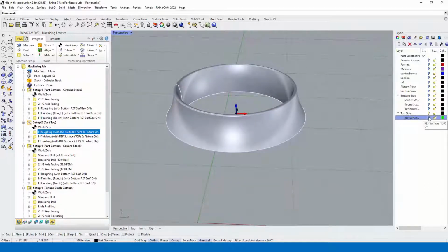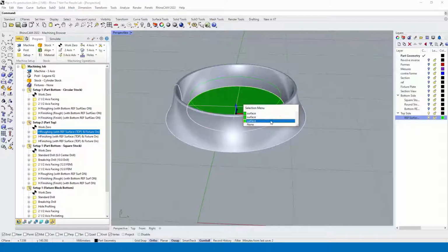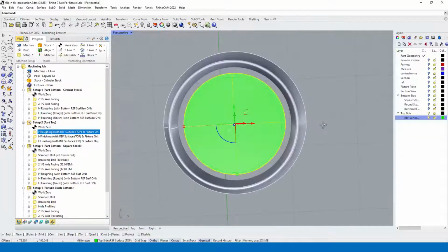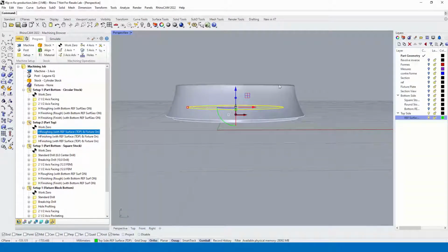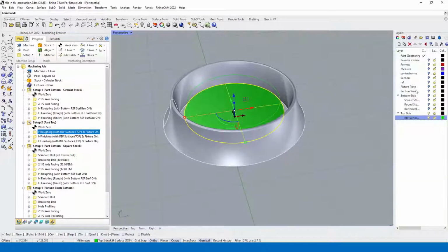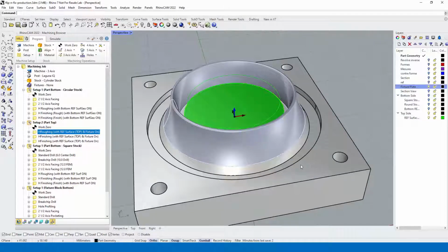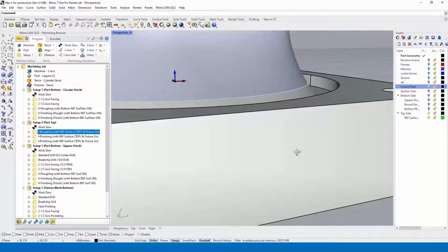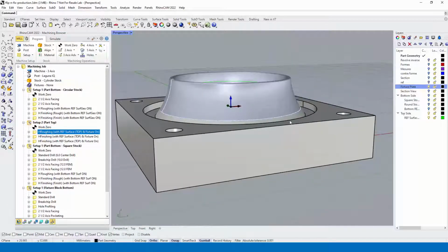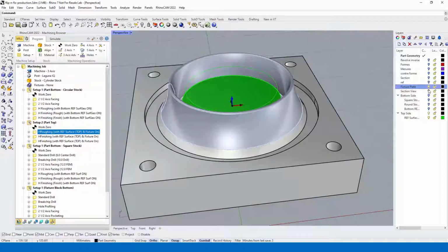Okay, top side. So here's just a flat surface that's going to be a place for the tool to land on. It's oriented past the quadrant, on down a little bit in the part. And let's go ahead and look at the fixture again. This surface right here, which is part of the fixture, is actually going to guide the tool past this edge. So you're going to maintain a sharp edge here as required by the part. Okay, so let's turn the fixture on. We'll turn that off.